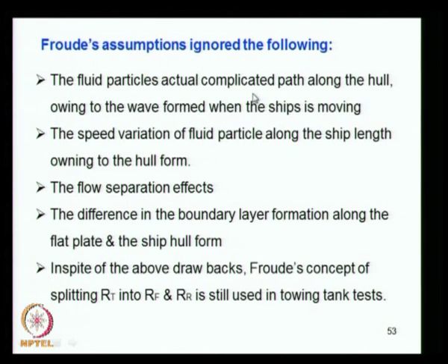So, here we considered that when the ship moves, waves are formed, and the fluid particle path may become wavy in form. It is different from the case of a free stream flow, that is, the submerged case when there is no wave. So, that path variation of the fluid particle is ignored when you bifurcate the problem into residual resistance and frictional resistance.